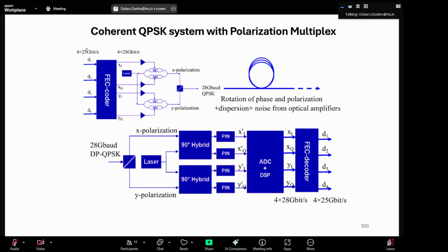In this case, it is 3 gigabits per stream, and eventually you add an extra 12 gigabits. So your data rate in the stream is 112 gigabits per second. The useful data out of it is 100 gigabits. So 12 gigabits is forward error correction overhead used to compensate for errors.